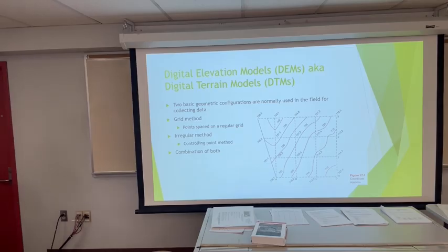As you get more experience doing this, you'll do all of that all at the same time. But when I had young college students out and was teaching them about topo, I'd get them working on it, show them what we're doing, and then turn them loose on a little area and say, okay, try this little area, focus on your break lines, fill in the blanks with ground shots in between. I think that helped them a little bit. I never had anybody complain at me about it.